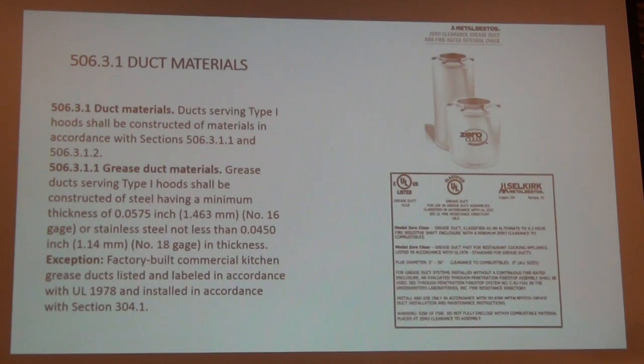We had a Marriott in Troy. We were getting calls from cars going down Big Beaver saying there were flames shooting 40 feet in the air off the roof of the second story part of the kitchen. What happened there is the fire suppression did not kick in. It was a lack of maintenance too. That always happens. But where the links were, when you do the pull test, the link was too close to the conduit fitting, so it wouldn't allow the pin to drop. So that's what happened there.